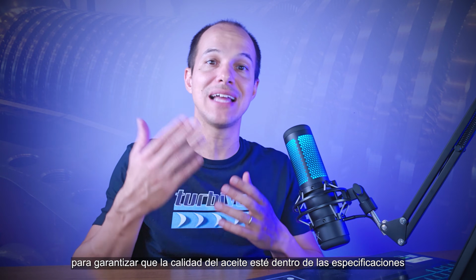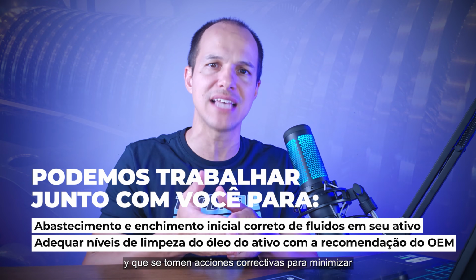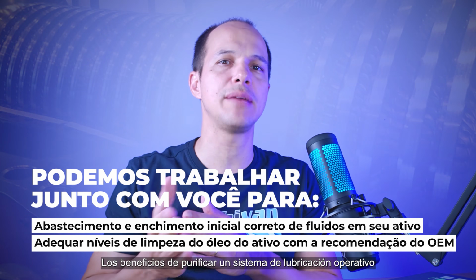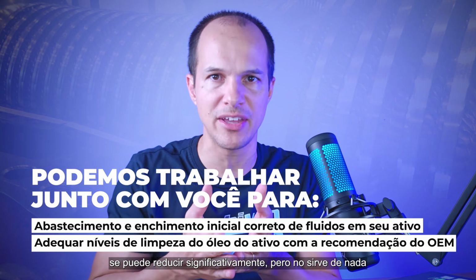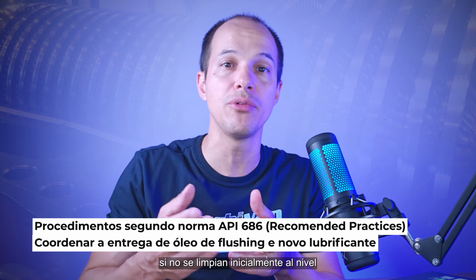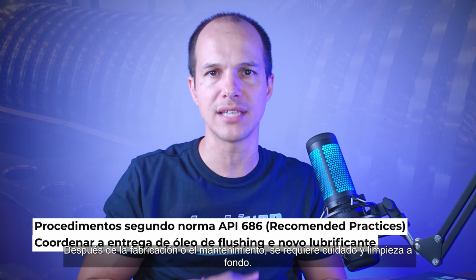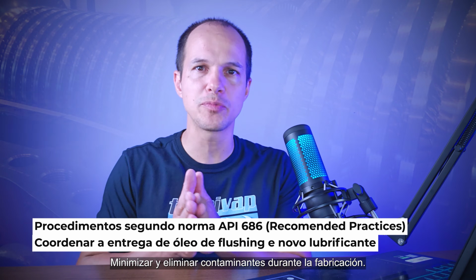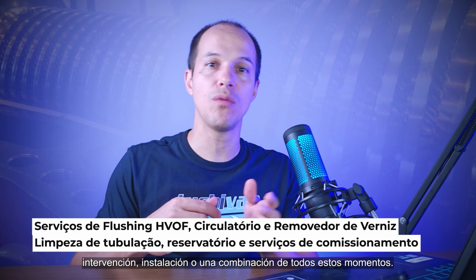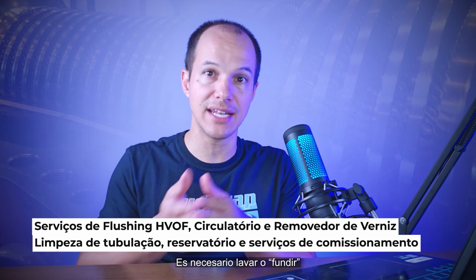In addition to an efficient purification system, a continuous monitoring program is also necessary to ensure oil quality is within specifications, and that corrective actions are taken to minimize the formation and entry of contaminants into the system. The benefits of purifying and operating the lubrication system can be significant, but it's no use if it is not initially cleaned to the level which will prevent damage to components on initial startup. After manufacturing or maintenance, thorough care and cleaning are necessary to minimize and remove contaminants from manufacturing, intervention, installation, or a combination of all these moments.